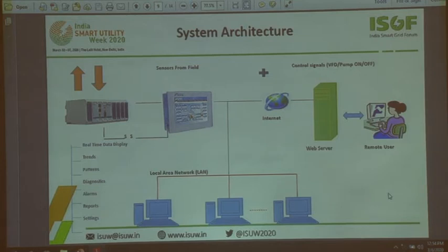Actually, sir, nowadays technologies are available to pull the data. Sir was telling how we get the data and monitor the flow, but how do we get the flow to the control room? Nowadays, there are small remote terminal units, small devices which can be mounted right at the device and powered with a battery.